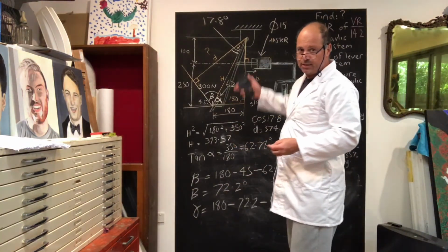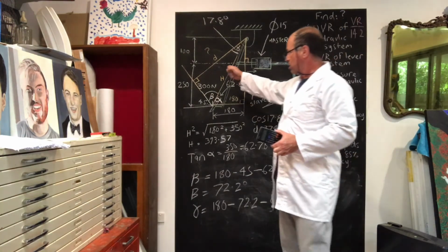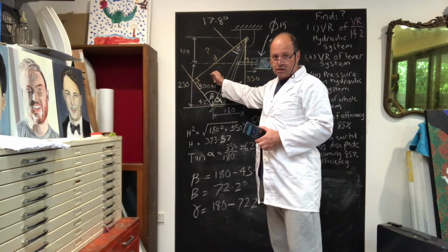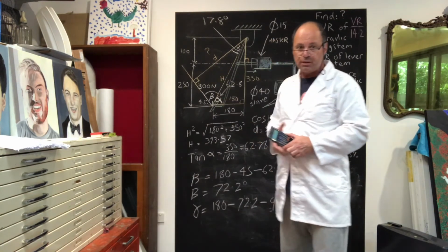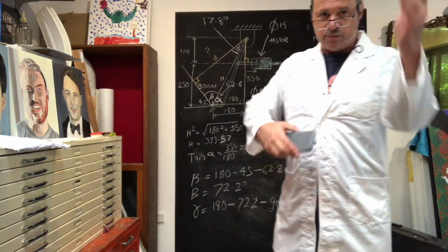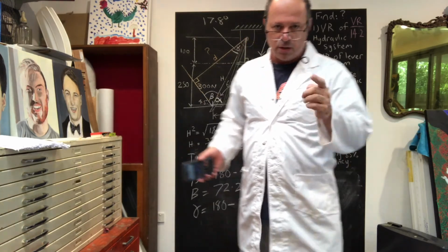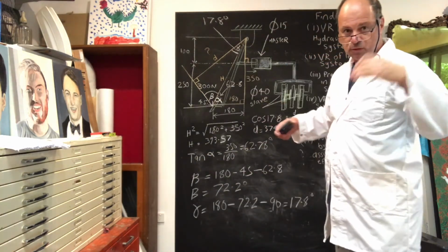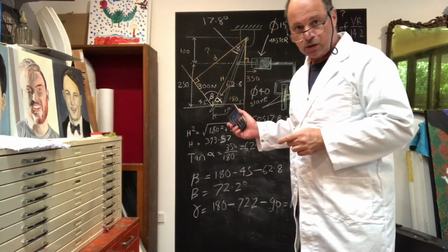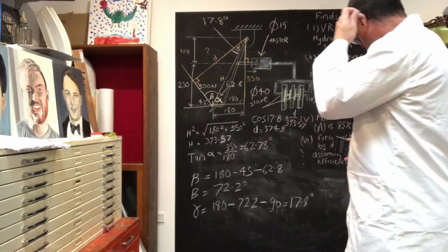But the main thing you need to understand with any of these types of questions is, if we're calculating velocity ratios, you need perpendicular distances to the pivot. So when everything's nice and horizontal and vertical, simple. When you've got situations where forces are inclined, you're going to have to calculate that perpendicular distance, okay?